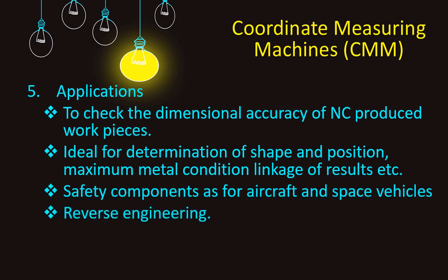And the last one is, it is used for reverse engineering. We know that a complete 3D geometric model with all critical dimensions can be built where such models do not exist. Once the geometric model is built, it becomes easier to design dies or molds for the manufacturing operations. So CMM is very useful in reverse engineering.